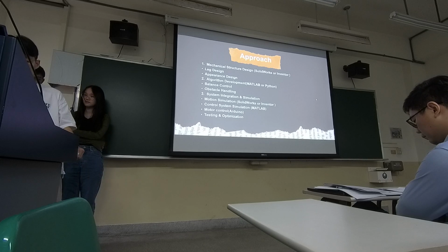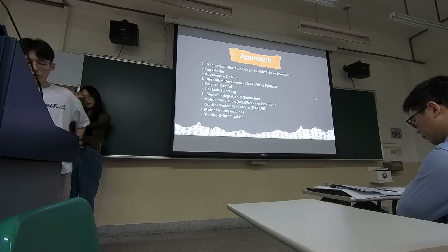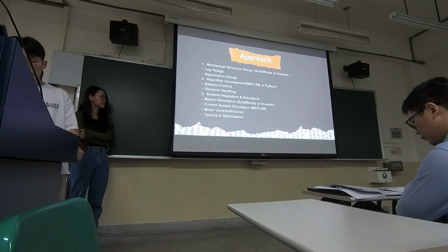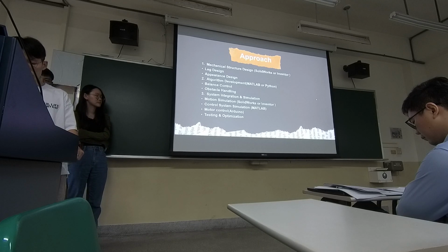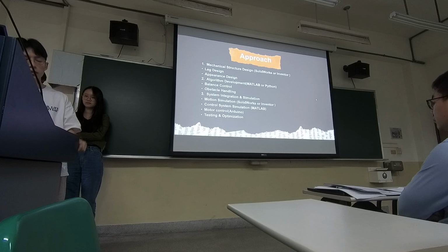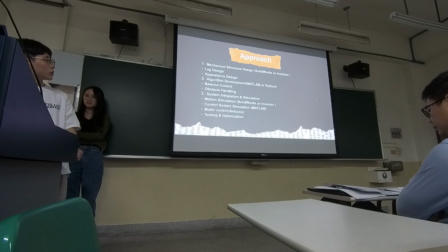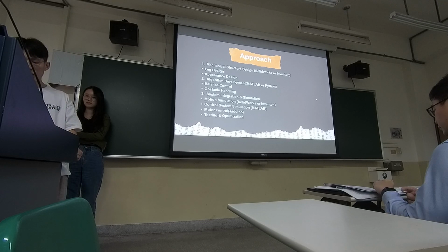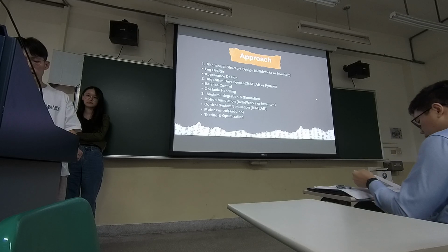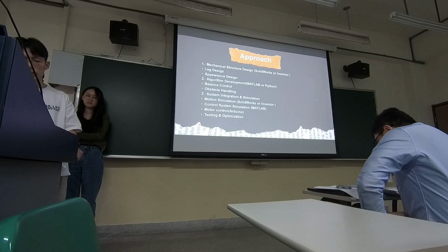We'll use MATLAB or Python in this part. In balance control, implement a feedback-based control algorithm, such as PID control, to adjust the robot's movement and maintain balance based on the virtual center of mass. In obstacle handling, devise strategies for overcoming obstacles by adjusting the leg movement while maintaining overall stability.